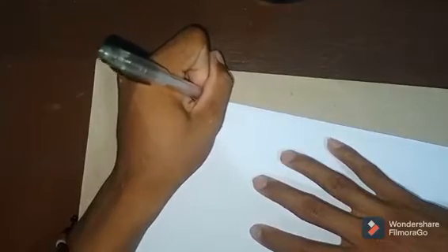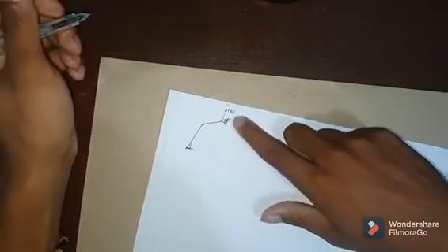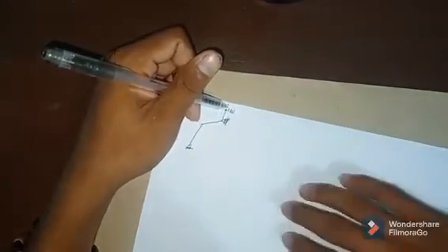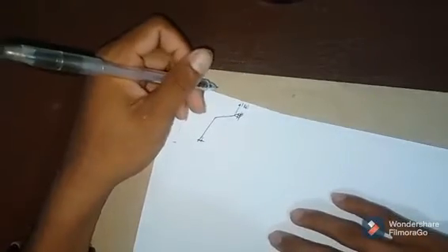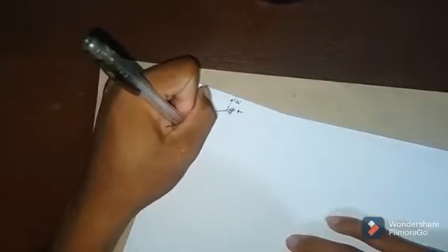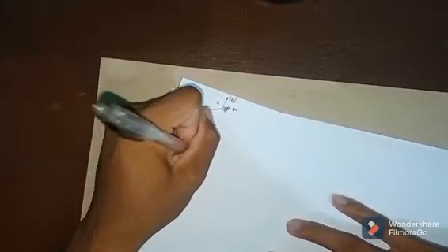So there is a displacement. We know that it has horizontal and vertical reactions. So summation of moment, we just label it as A and B. So summation of moment at A equals 0, counterclockwise positive.